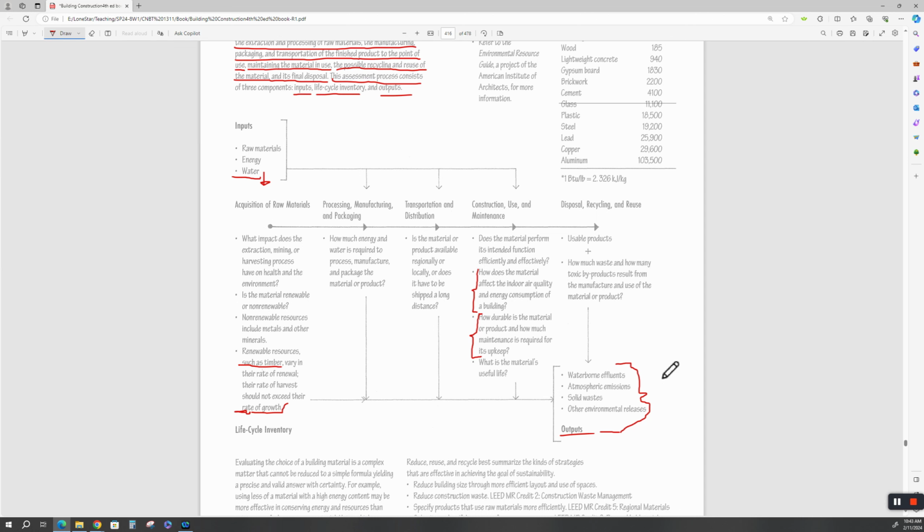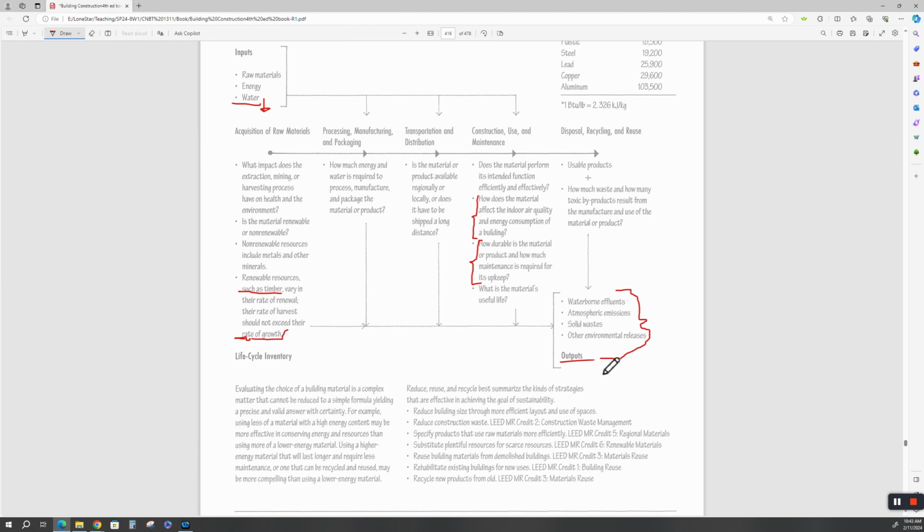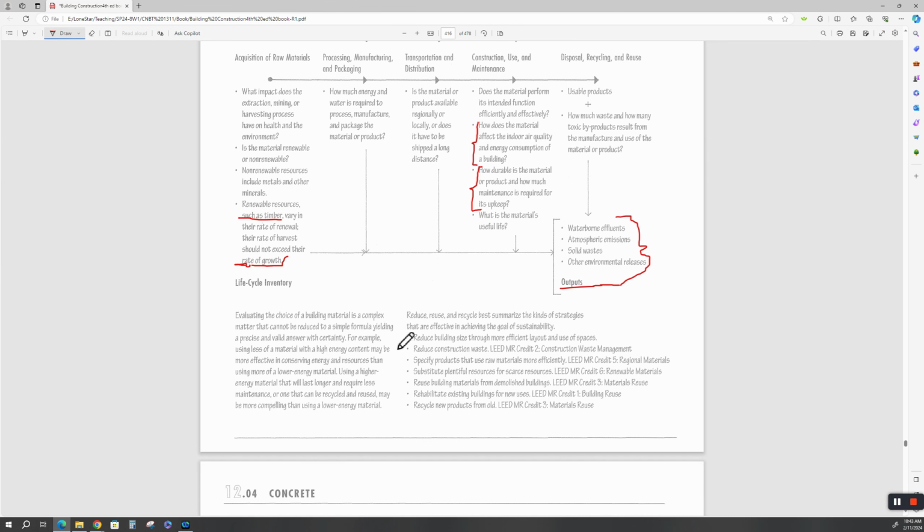When I did my kitchen floor, I had a feeling that that old tile in the kitchen, vinyl tile, was asbestos. When my flooring guy got in, he said, yeah, it probably is. So we floated over that, and we roughed that stuff up, floated over it, and then put the new high-tech composite vinyl over that. We encapsulated it. All right.